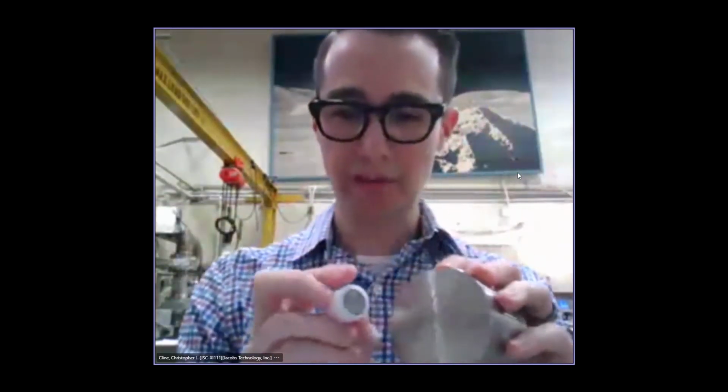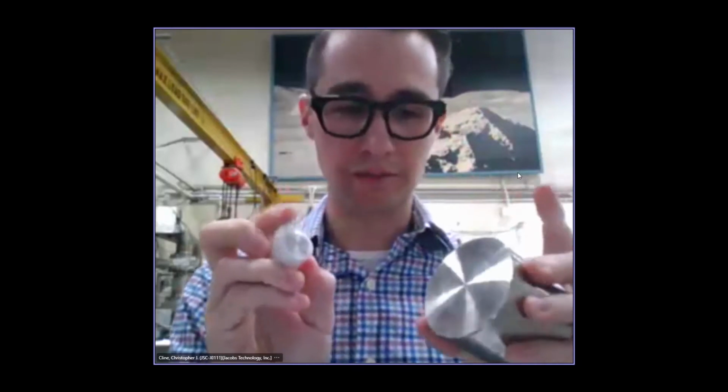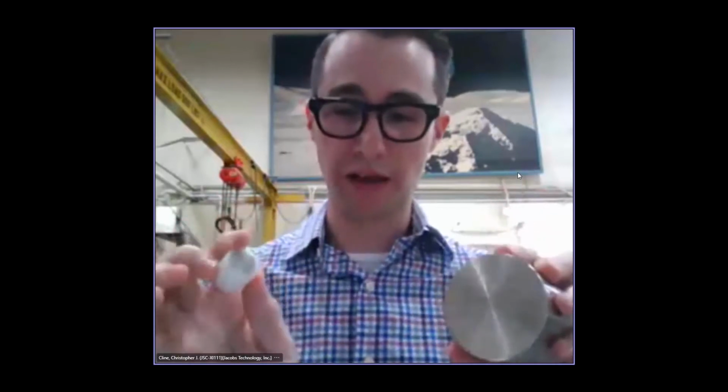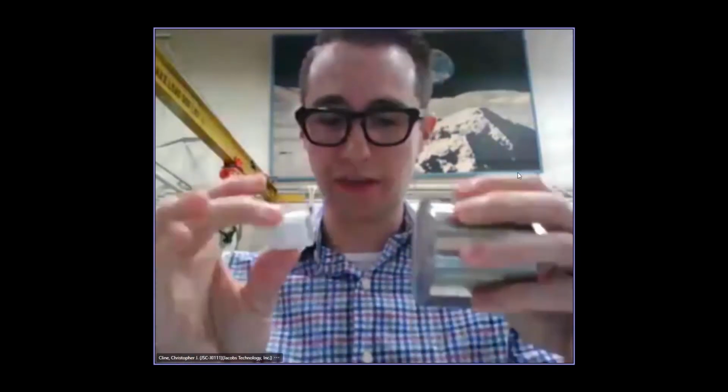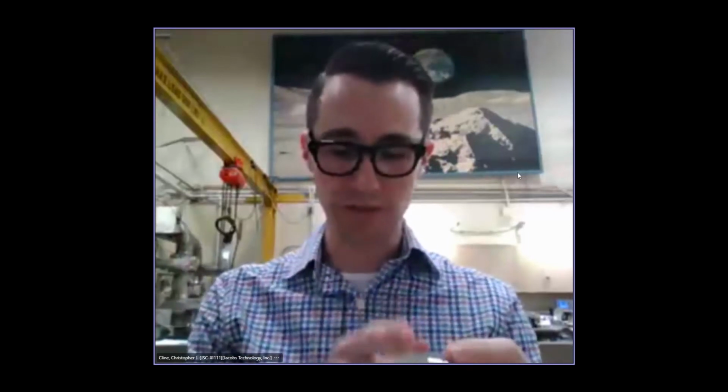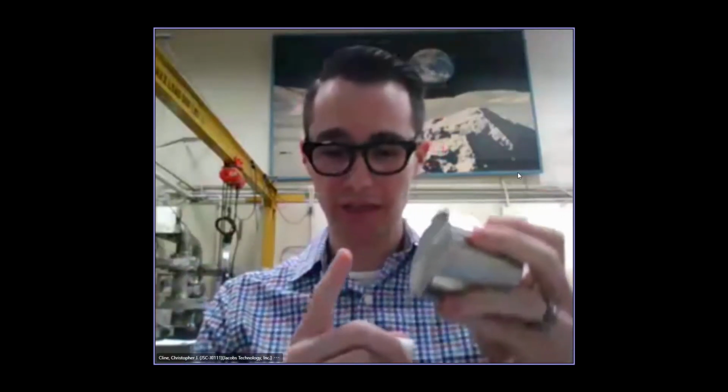Now, when that impact happens, you have a thermodynamic state that's reached between these two metals that's dependent on how fast this projectile is going when it impacts. And if it impacts nice and flat, we know the pressure that would be generated by those two metals impacting at that speed. And since your sample is in the middle of this metal container, it will equilibrate to that pressure. After this impact happens, we can machine away some of this metal, extract out your sample of rock, give it to the investigator, and they can go off and do what they will with it, look at microstructures or spectra or whatever they're interested in.